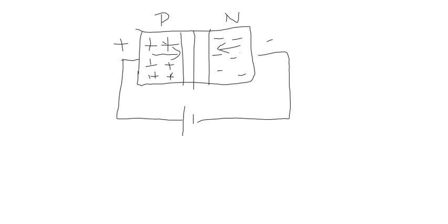So what happens is, if you have enough voltage here on the supply, you'll actually collapse the depletion region and start to have a current flow. Guess how much voltage it takes to collapse that depletion region? The 0.7 volts of potential that's developed across it.